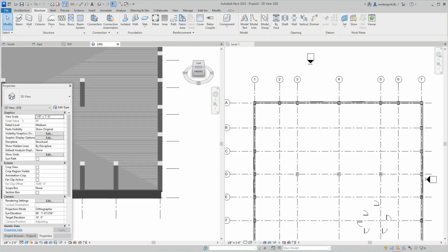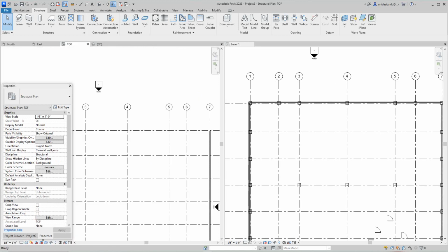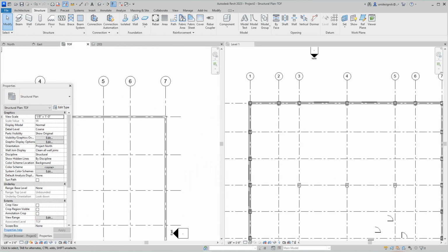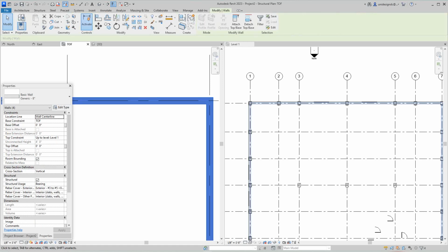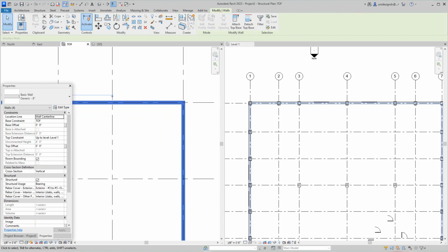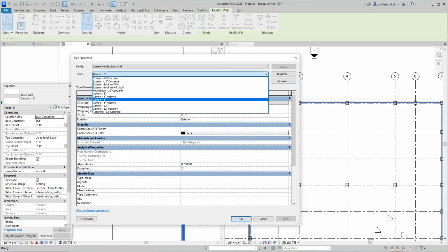Now we need to go in and look at this and see what the thickness is. We've got, let's see, that's an 8-inch. Oh, we need a bigger wall than that. I think in that detail we were at 14 inches. So tab. So what I'm going to do is edit this type. First of all, I want a structural wall here. 12-inch concrete.